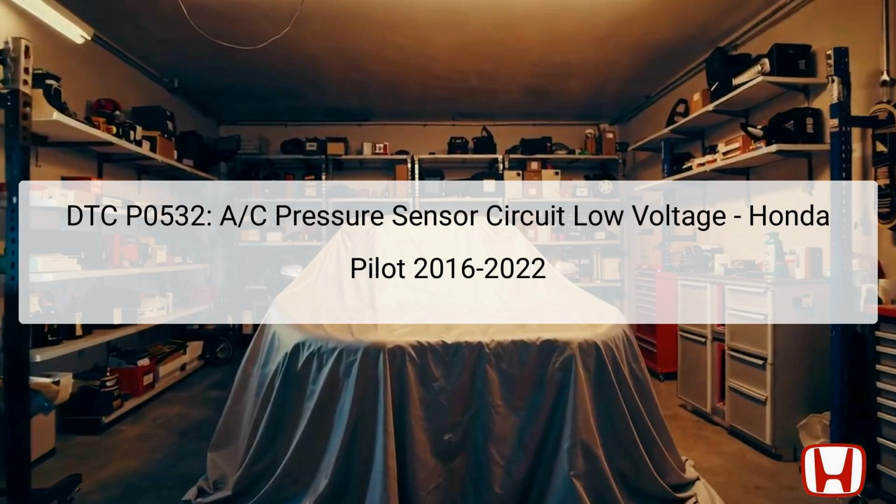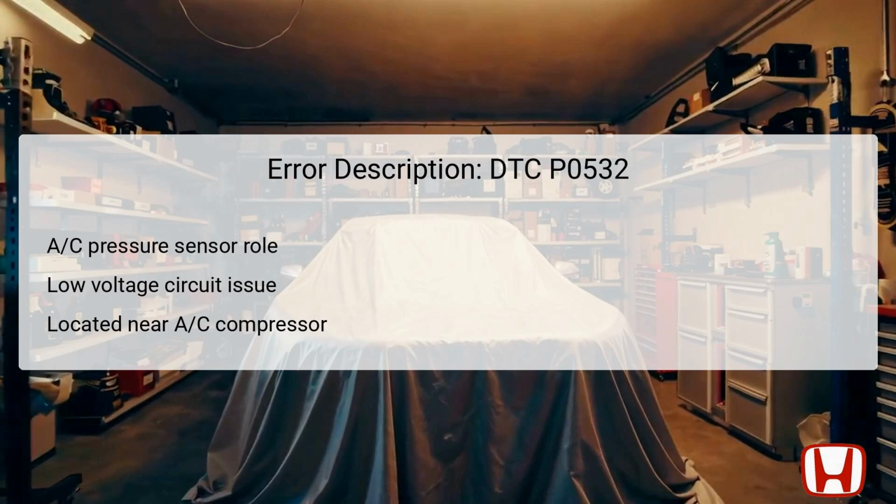The AC pressure sensor plays a crucial role in the vehicle's air conditioning system by monitoring the refrigerant pressure and sending this information to the powertrain control module, PCM. A low voltage condition can affect the functionality of the air conditioning system, potentially leading to inadequate cooling performance or system failure. Our goal is to systematically troubleshoot this DTC in a structured manner, ensuring that each component is thoroughly checked for functionality. The DTC P0532 specifically points out a low voltage issue within the AC pressure sensor circuit.